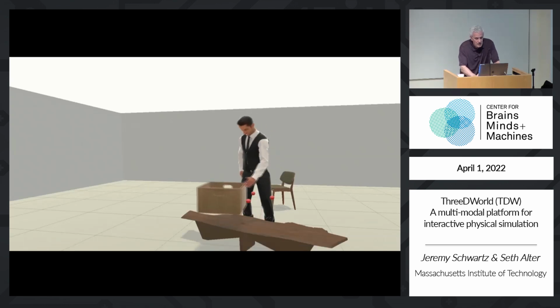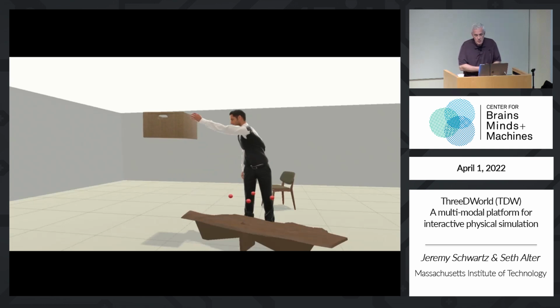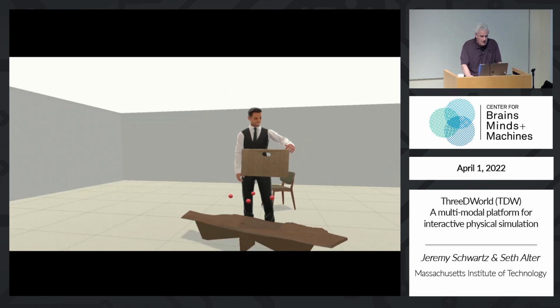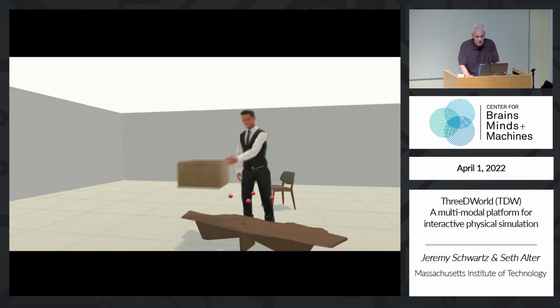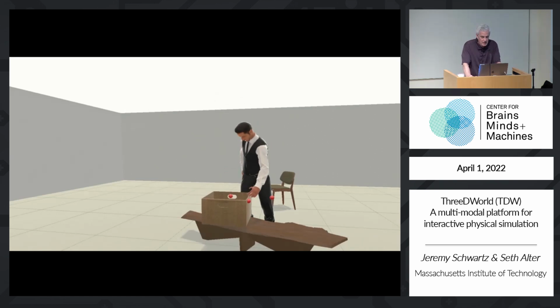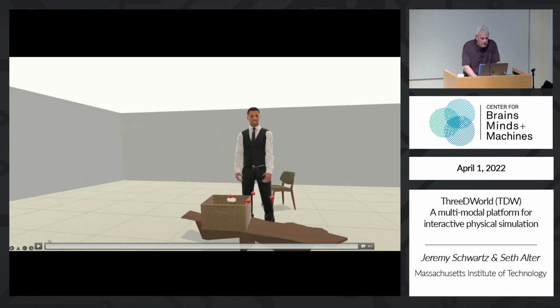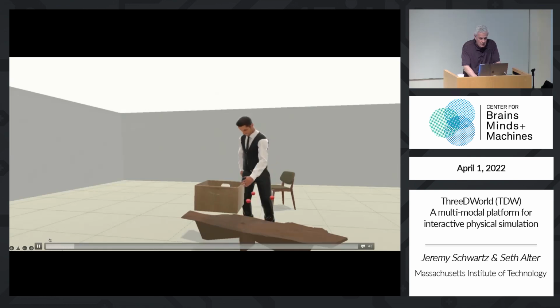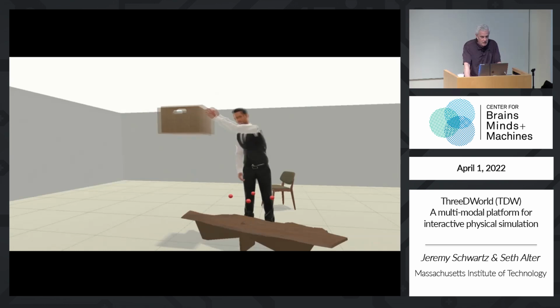So here we're combining our reach action with systems for assigning affordance points to objects and maintaining the stability of held objects such as containers. The basket in this image has 4 important affordance points defined. The system can either use an explicitly labeled affordance or else select the closest one to the agent's end effector, depending on its orientation with respect to the basket. Affordance point locations are defined as JSON object metadata and can therefore be easily adjusted at any time. As the agent reaches for different target locations, the stability of the held container is being maintained automatically.